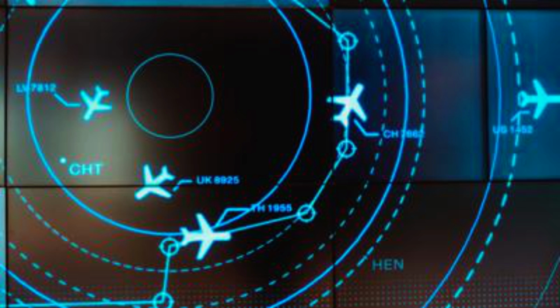When planning for a departure, pilots should: 1. Consider the type of terrain and other obstructions in the vicinity of the airport. 2. Determine if obstacle clearance can be maintained visually or if they need to make use of a DP. 3. Determine if an ODP or SID is available for the departure airport. 4. Determine what actions allow for a safe departure out of an airport that does not have any type of affiliated DPs.